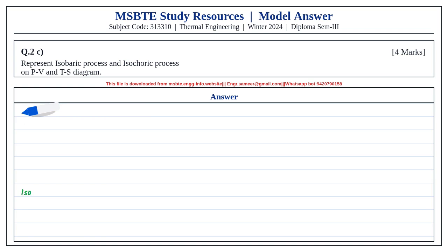Question 3C. Explain construction and working of forced draught cooling tower with neat sketch. Forced draught cooling tower consists of a fan, spray nozzles, circulating pipe, water tank, eliminators and pump. Hot water is sprayed from top. Air is forced upward by a fan placed at the base. Air and water flow in opposite directions. Heat is rejected to air and cooled water is collected at the bottom.